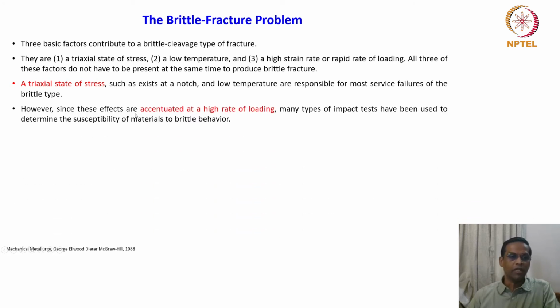However, since these effects are accentuated at high rate of loading, many types of impact tests have been used to determine the susceptibility of materials to brittle behavior. So this is a kind of an acid test to check whether the material is going to behave or it is going to failure by a brittle fracture. Okay.